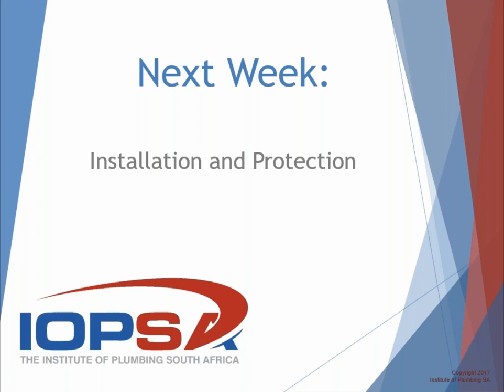I would almost argue that it's a critical part of the installation, but if it's of a sufficient quality and it meets the R requirements, and we install it properly and we take proper care of it, I would be hard pressed to come down on that plumber and say this isn't SABS rated stuff. You can't use it. You know, the SABS rating of components and pipework is for me of big value. It resides in the pipe, in the fittings, in the geyser, in the valves, etc. Those sorts of things that can catastrophically fail. But the lagging, as long as it's fulfilling the requirements, I would not make a big fuss about it.